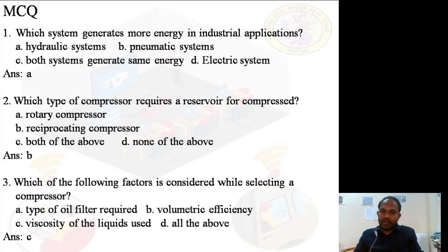In the food based industrial applications, obviously, in such cases, if the same option is being given, I would say the pneumatic systems, as we discussed earlier. In most of the food industrial applications, they use the pneumatic systems, only because the leakage of the oil will not be there, as happens in hydraulic systems, and it is not polluting any of the food contents, is it not?